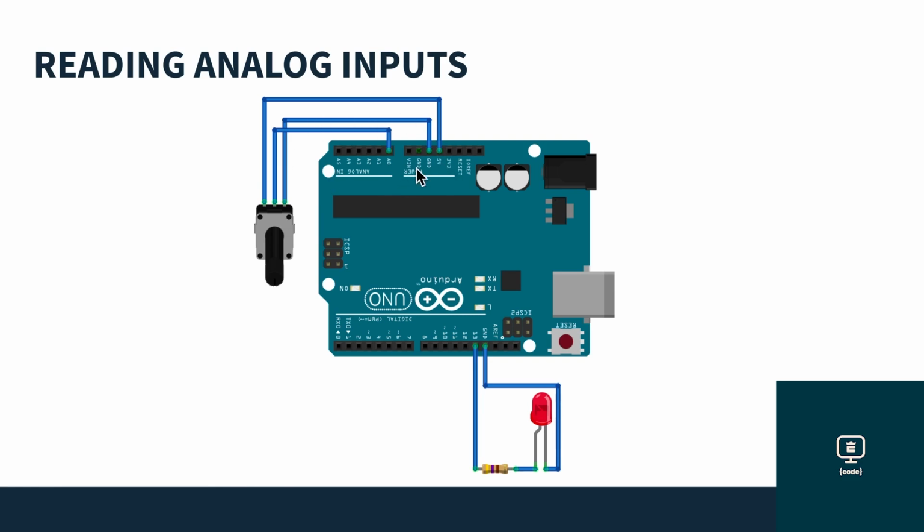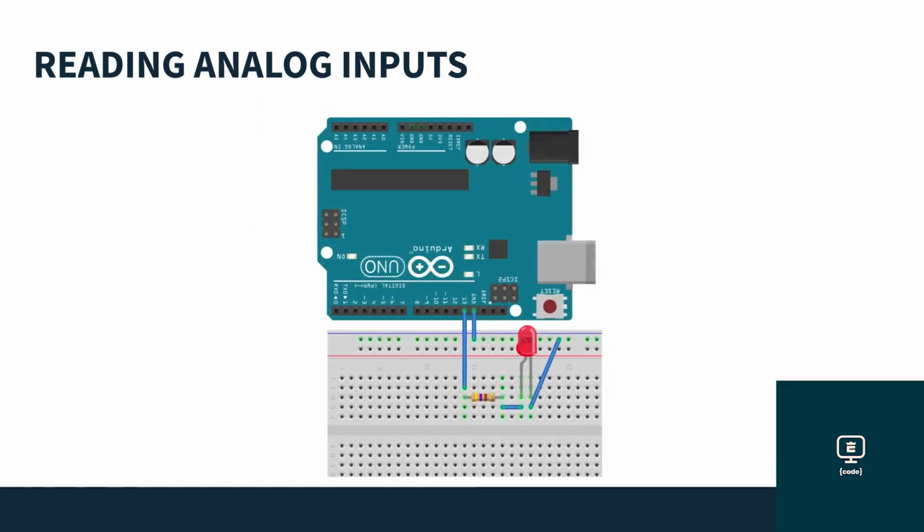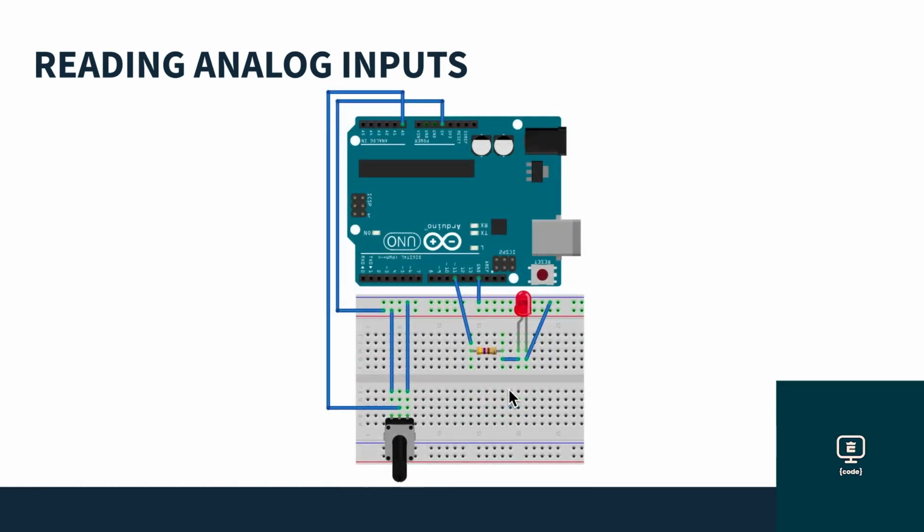What's it look like on the breadboard? So here's the circuit for the LED. To add the potentiometer, it would look something like this. Again, coming out 5 volts. That 5 volt connection is coming into the positive bus. That signal is going into this first terminal. Then coming out of the last terminal is going into ground, which is still connected here on ground. And then the middle terminal, the wiper, or sometimes it's called the cursor, is actually what's going back into analog 0. So let me show you how it turned out on my board.